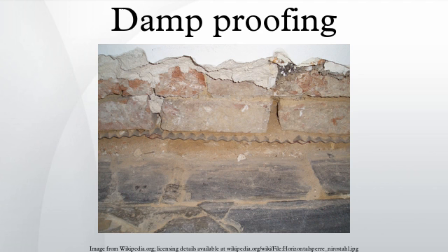In a masonry cavity wall, there is usually a DPC in both the outer and inner wall. In the outer wall it is normally 150 mm to 200 mm above ground level. This allows rain to form puddles and splash up off the ground without saturating the wall above DPC level. The wall below the DPC may become saturated in rainy weather.